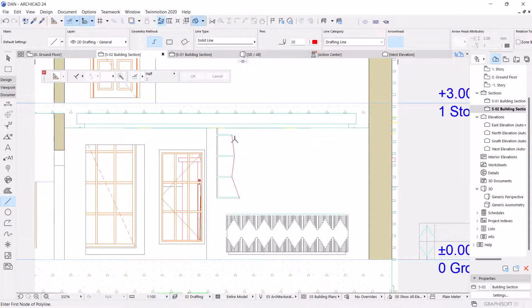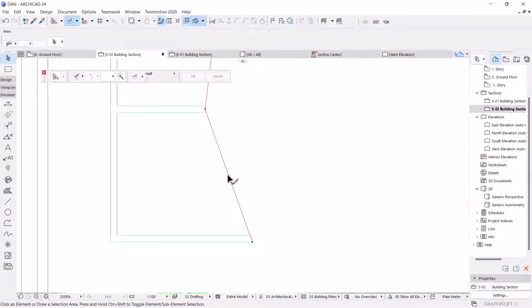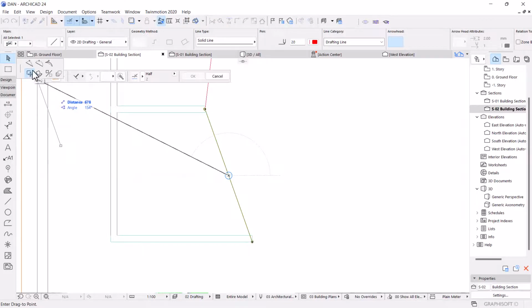Okay, now I'm going to suspend groups, and once I have suspended groups, I click on it and I want to curve it. So you click on the section of the line that you want, and you can click anywhere. So I'm clicking at the center. Once you click, it gives you a number of options. Right now it's on the drag option, but I want the curve edge.